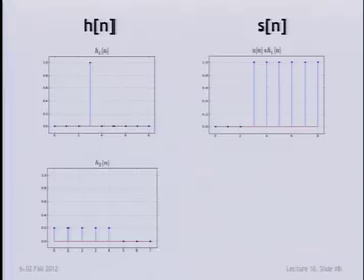So here's another unit sample response. This is more complicated now. I put in a unit sample, and what comes out is a response that still starts at time 0, so I'm talking about a causal system. Everything to the left is 0. And this takes the value 0.2 for some number of steps, and then settles to 0.